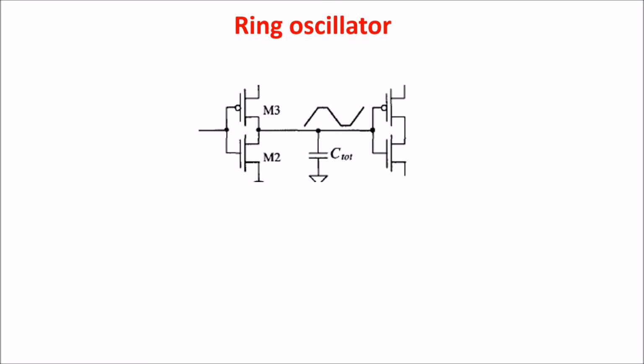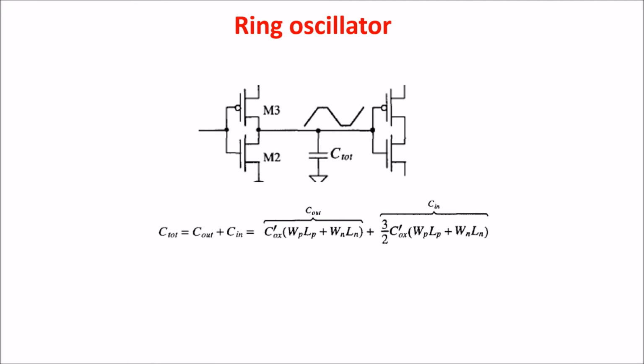The second feature of the ring oscillator is the delay introduced by the inverters, which is defined by the capacitive load given by the input and output of each stage, and it is proportional to C oxide and to the length and section of the channel of the P and N MOS. This means that the output of the inverter will take some time to update the value after the input changes, so the circuit can hold the logical contradiction for a period of time. The delay of each inverter is calculated as the time needed to charge and discharge the capacitor up and down.